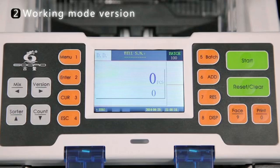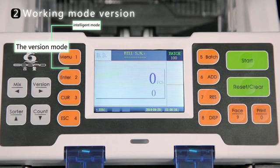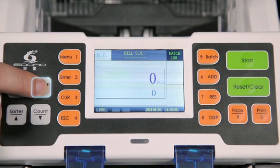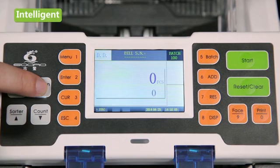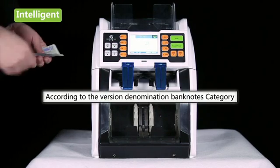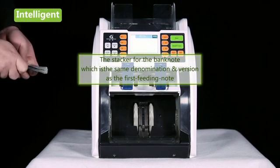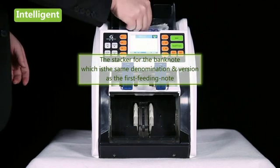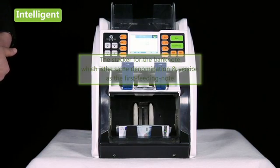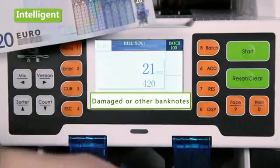Working mode version. Intelligent version mode. In the standby interface, press the version key to switch to a different function mode. The LCD screen will display the selected version mode. 1. Sort denomination and version (DD). The machine automatically takes the first fitting note as a reference standard, sorting banknotes of the same denomination and version. The stacker is for banknotes of the same denomination and version as the first fitting note. The reject pocket is for suspected, damaged, or other banknotes.